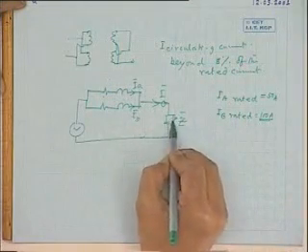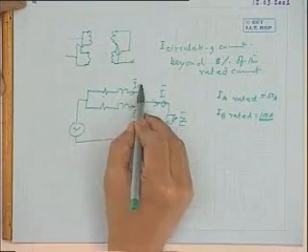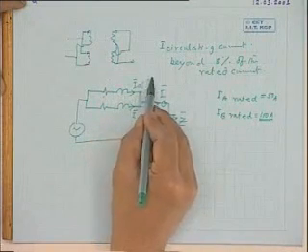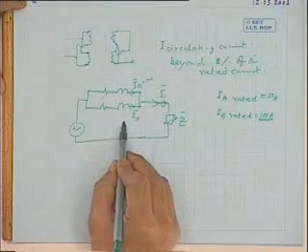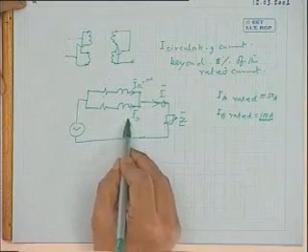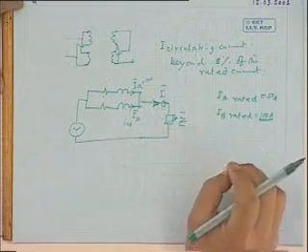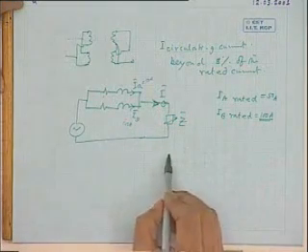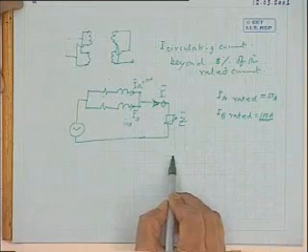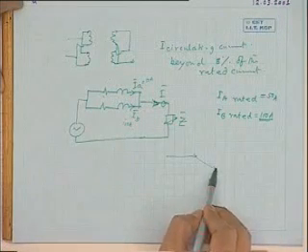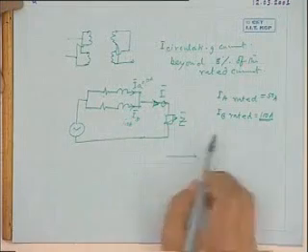What I am trying to tell, when you vary this load, and suppose this current is set to 50 ampere here, and this current is set to 100 ampere here. What I mean to say, the current here to the load will not be 150 ampere, because of the fact that these currents will be added at some angle.